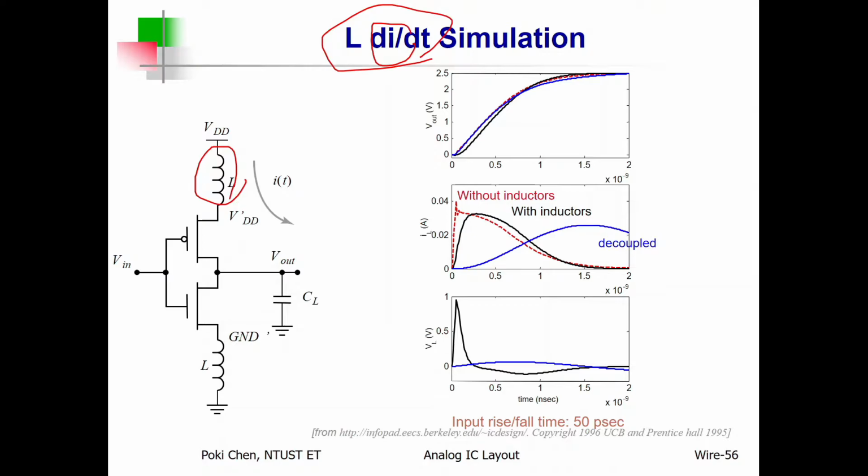So how do we solve the problem? You either reduce L or reduce di/dt. It means you need to slow down the change of the current. If not, you need to face the big voltage drop. That is what I recommend.